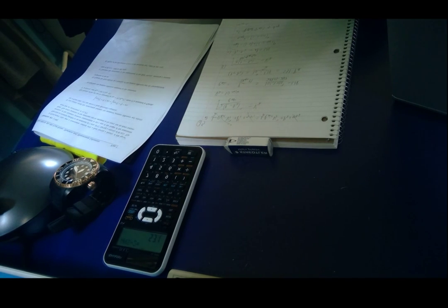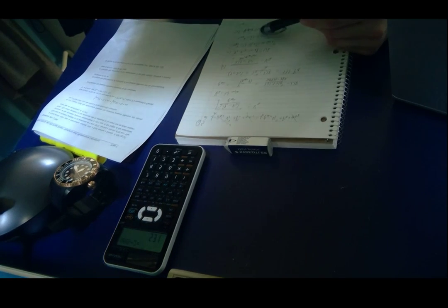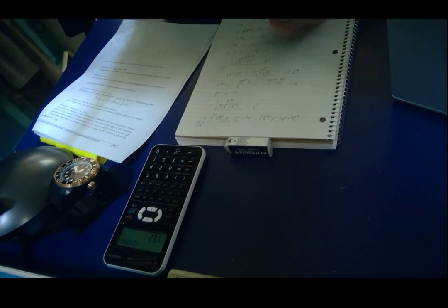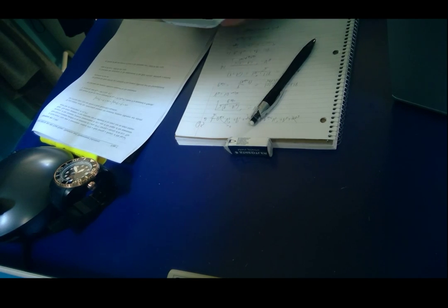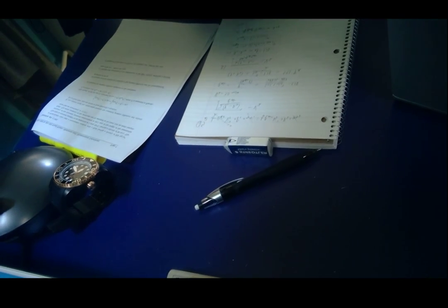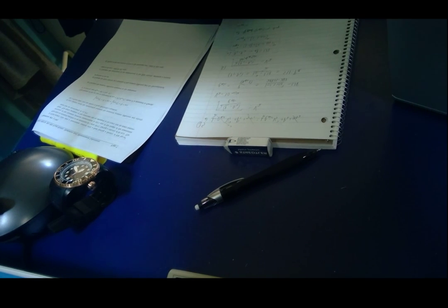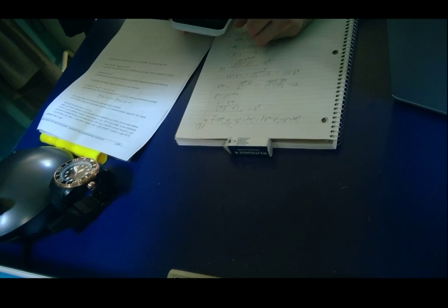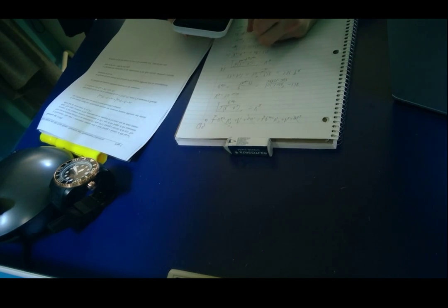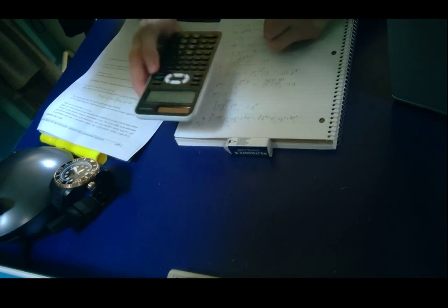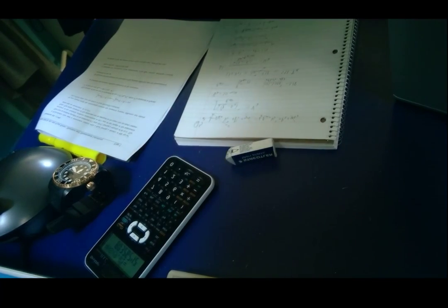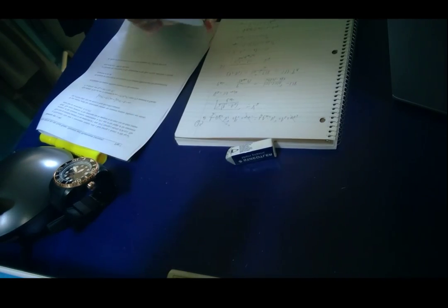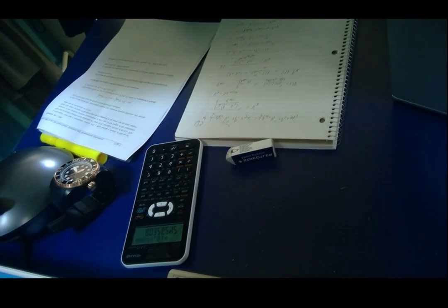So we're going to have, well, there's this 0, this is a constant. So we'll just do our 820, which is the density of the fluid used in the manometer, minus the density of the air, which is 1.18, times 9.81, because we are using the SI system. That's 1,332.6 times delta Y. It's a very straightforward thing.